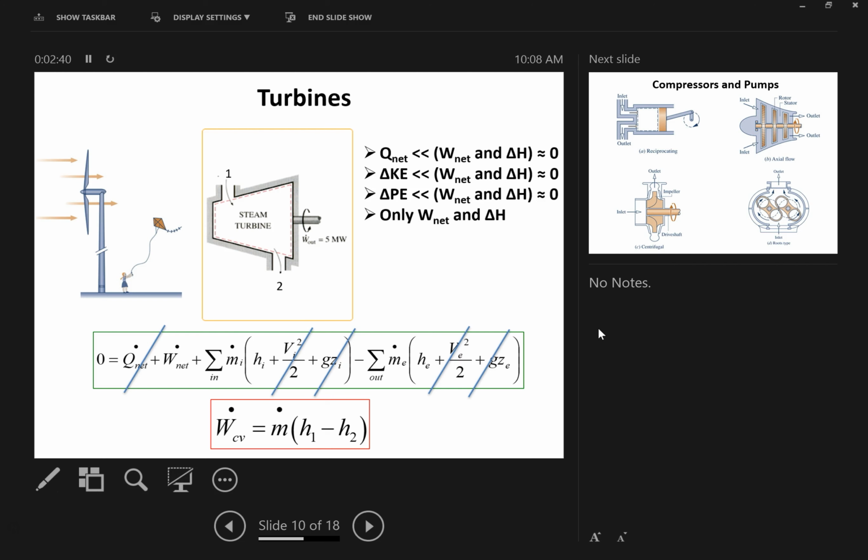They take a turbine and throw it in that cycle. They have two heat exchangers and a boiler. So that's their cycle. Once you analyze this, you can figure out how much output you're getting from your cycle. Again, we're going to start with the first law and break everything down and then get to what we want.